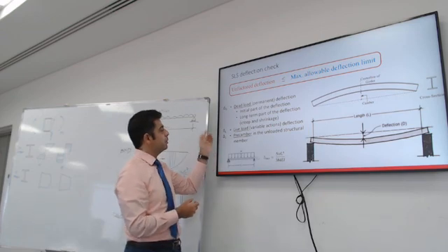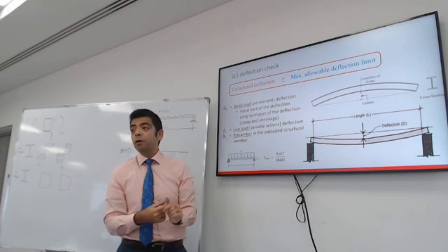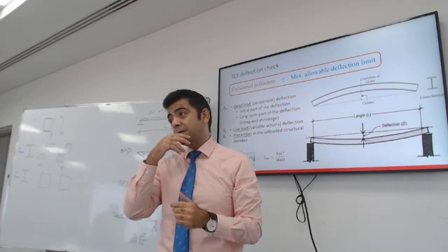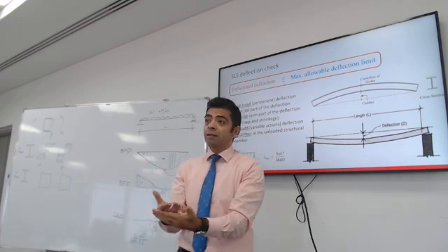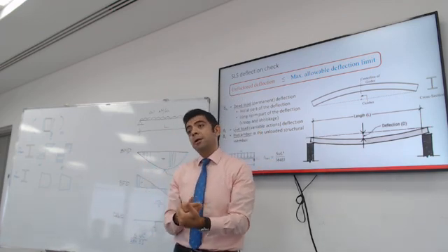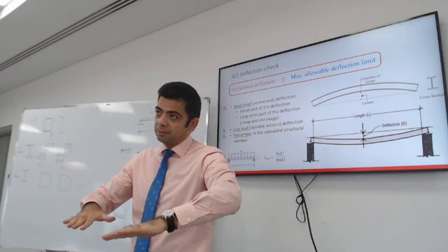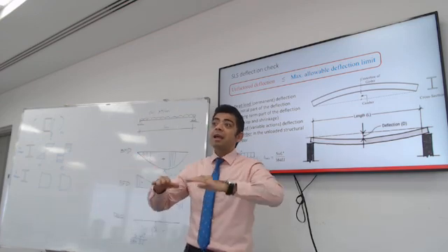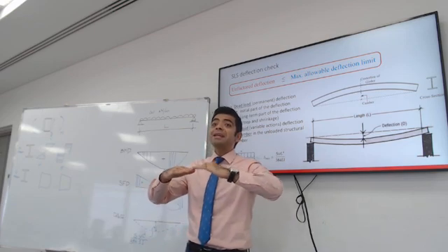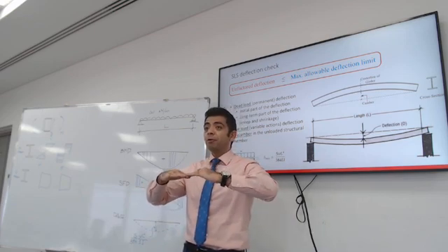The second type, you probably guessed it, it's live load deflection. So the deflection under our own weight. This deflection is not permanent. When we walk into the room, the floor will deflect. When we leave the room, if the deflection is within the elastic limit of the floor, it will rebound.